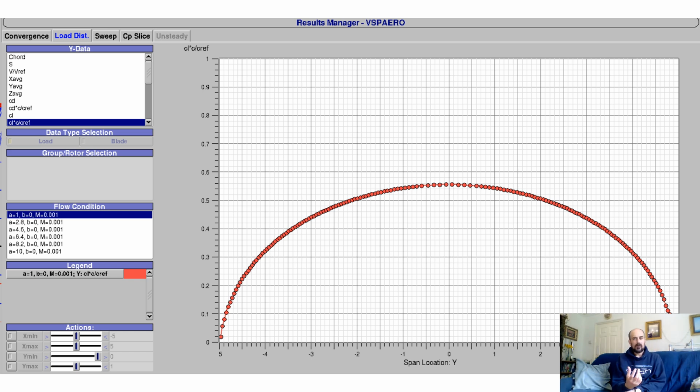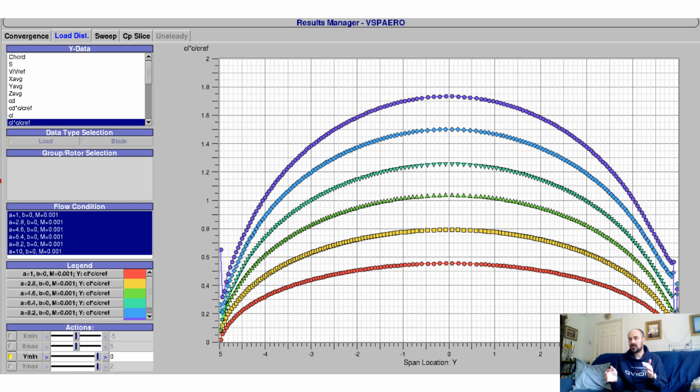There is still some advantage to having an elliptical shaped wing though, because that gives you the elliptical distribution of lift across a very wide range of angles of attack. Whereas if you're achieving the elliptical lift distribution by tweaking the twist distribution, then you can only get that to give you a truly perfect lift distribution at one single angle of attack, and so at one single speed. At any other angle of attack or any other speed, you're going to be off that perfect distribution to some extent.